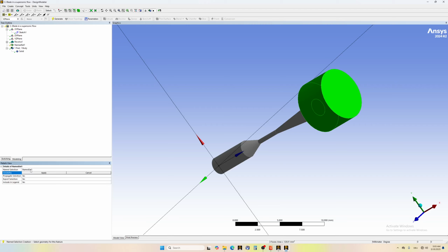So we just define the boundaries. You can do it now or you can do it in the meshing program, but let's do it now, and let's call it pressure outlet. So it's 3 faces, 1, 2, and on the back 3.